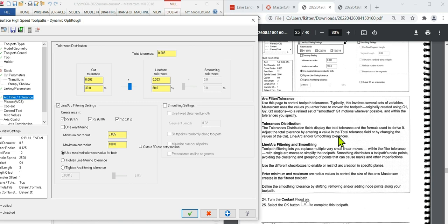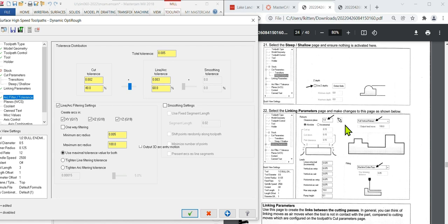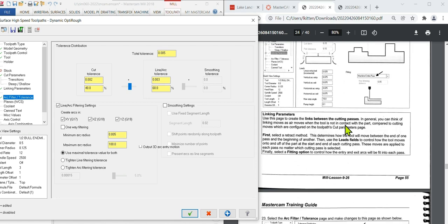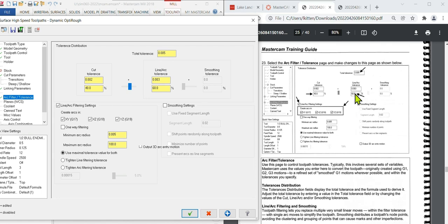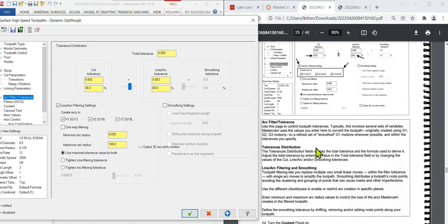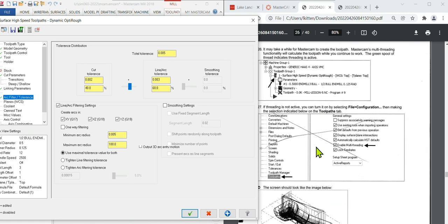But nothing matches up. But just do the tolerance. Cut tolerances and everything. If you do the tolerance and then you do 60%, it should fix it. Sometimes on those you'll have to play around with it to get them all. You'll click one thing, get it set, then click another button, and it'll reset them all back to where they were, and you gotta go back to it. I think if you do these two main ones, 0.005 and 60, it all matches pretty good. Usually it'll all match up.